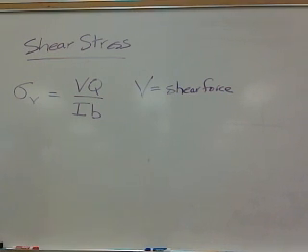Where do you think we might find the shear force? If I have a beam and I say, hey, determine for me the maximum shear stress. Well, again, the maximum shear stress is only going to occur where the shear force is maximized. Where would that happen? Or where could I find that out? Would it be where the load is placed on it? No, not necessarily. Have we done anything that might tell us what the magnitude of shear is? How about a shear diagram? Okay? So again, just like bending stress, where you might take the bending moment off the bending moment diagram, with this formula, the shear force very well could be taken off the shear diagram.